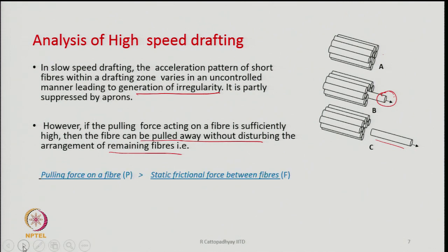And for that, the pulling force on a fiber must be much greater than the static frictional force between fibers. P is the pulling force and the static frictional force between fibers is F. If P is much more than the static frictional force F, then the fiber will be withdrawn without disturbing the arrangement of the fibers which are left behind.